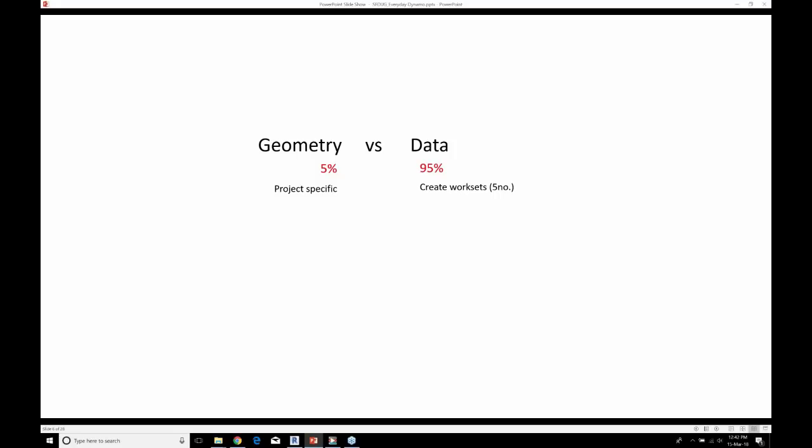So we can look at workset creation when you're creating your central model, assigning elements to that workset, having isolated workset views so you can start to monitor the team and how they're actually following the rules as to which element should go on which workset.